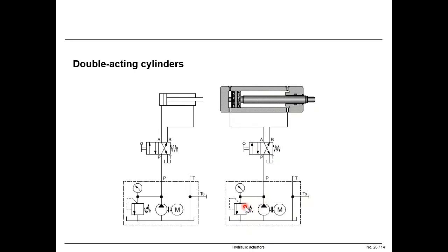We adjust the pressure for the system pressure level, and then we don't touch it. It comes from the producer of the power unit. The producer of the power unit makes this adjustment, and nobody should touch it and change it, because it is an important issue related to the safety of the system.